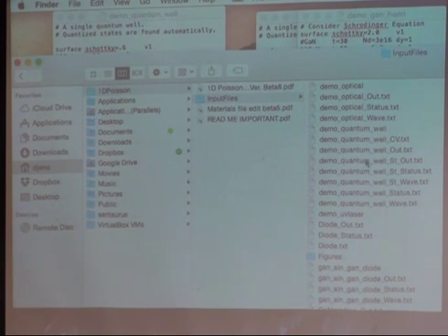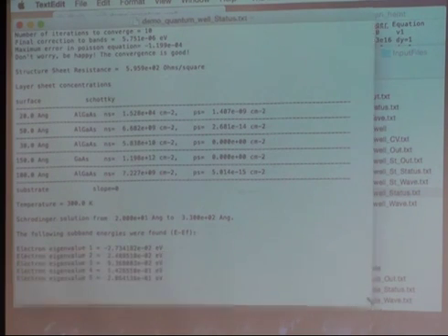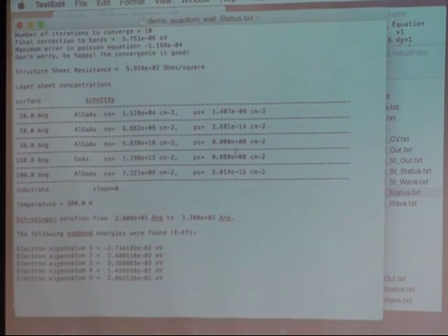What is the sheet density? For that, you can go here and look at the status file, because that gives you, in every layer, how many electrons and how many holes you have. Here, for example, is our quantum well layer, 15 nanometers of gallium arsenide. It's saying I have roughly 1.19 times 10 to the power 12 per centimeter square sheet carriers in that layer, integrated. Make sense?